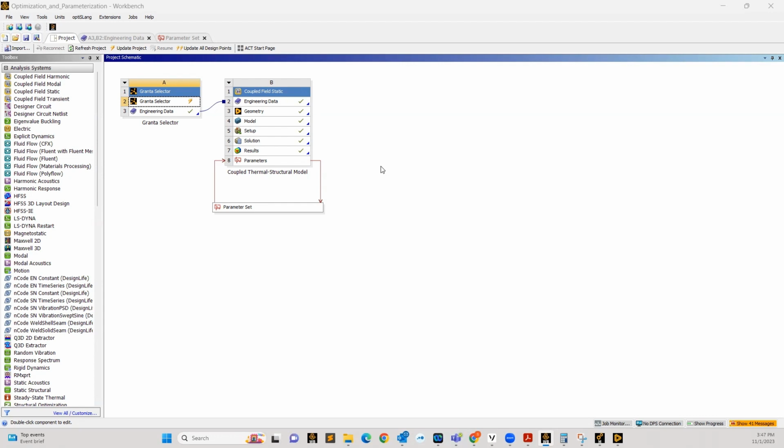It essentially allows us to define parameters in all sorts of ways, things like geometry parameters or boundary condition parameters, things like that. Those all manifest themselves in what we call design of experiments, which is essentially just a large table of values that we can change the values for the input parameters on to then tell us how those input parameters are going to affect our output parameters.